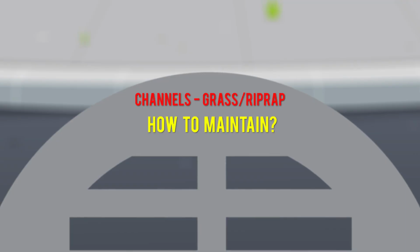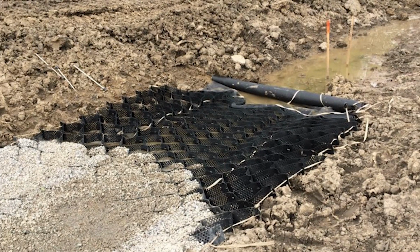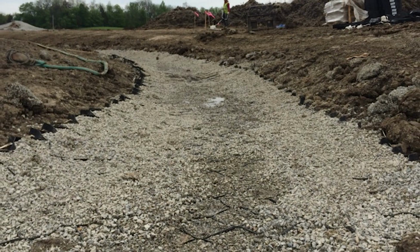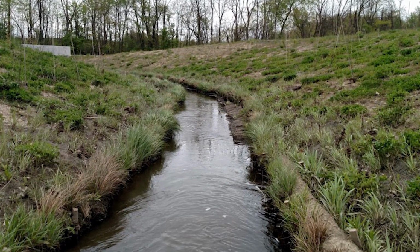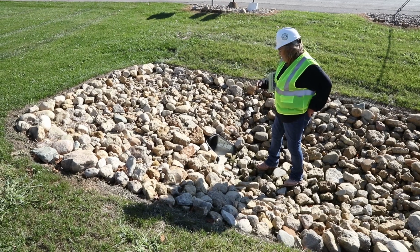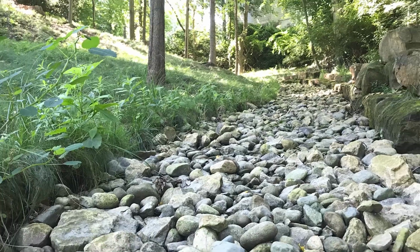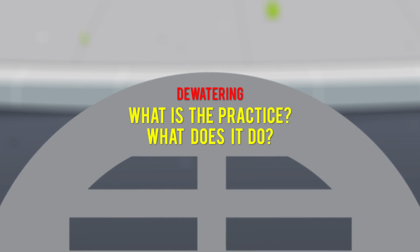How to maintain. Remove any blockage and make repairs. Stones may need to be replaced. Remove significant sediment and debris from channel to maintain design, cross-section, and channel grade and to prevent spot erosion. How to inspect. Inspectors should check channel outlet and road crossings for blockage, sediment, bank instability, and piping or scour holes.